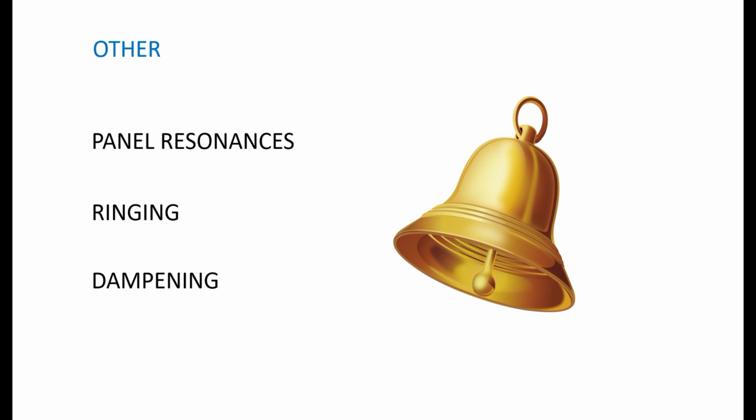Now, big cars suffer more from this than small cars because everything is bigger and wider and more surface area, right? But I guess in big cars, there's also more dampening in the cabin because you've got bigger seats and more carpet, right? So what can you do about all of this stuff? And the real answer is sound treatment, right? Sound treatment, so butyl to stop resonances, foam to stop surfaces touching and squeaking against each other, and mass-loaded vinyl to block sound waves, right?